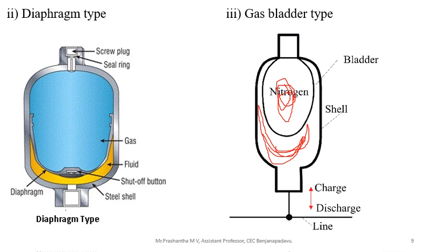As the requirement of fluid comes from the machinery or circuit, the nitrogen gas expands because of the pressure drop in the system. Because of this expansion, the pressure helps to push the liquid to the hydraulic system.